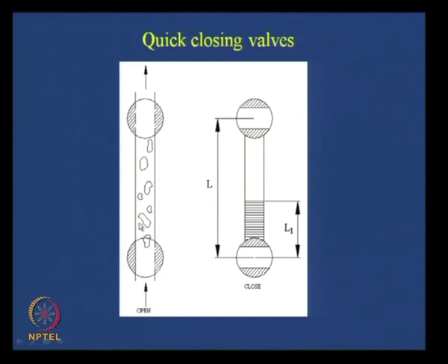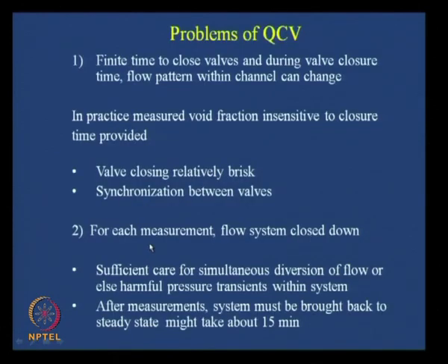Normally what is done is we can use two ball valves or maybe electrically operated solenoid valves, which is the best, because in that case one or two particular switching offs are going to stop the flow there. The other thing is, suppose you use mechanical valves, then they have to be linked up by some mechanical linkages, so that they can be closed simultaneously. So, these things have to be kept in mind.